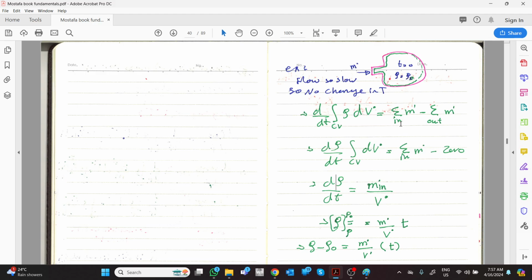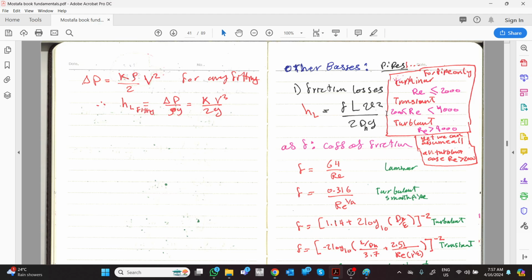Then if you have a type of flow which is very open, and you can approximate how it looks without a real boundary condition, maybe one or two at maximum, go with potential flow theory. But if you have a fully closed or semi-closed system like tanks, etc., use Reynolds transport. Okay, this is how we are going to think, how we are going to decide what we need to do.